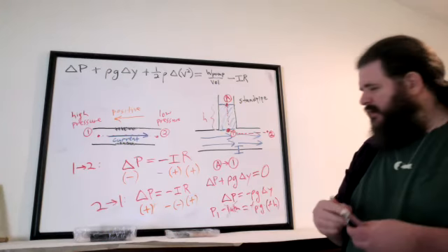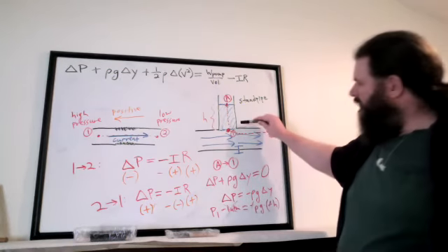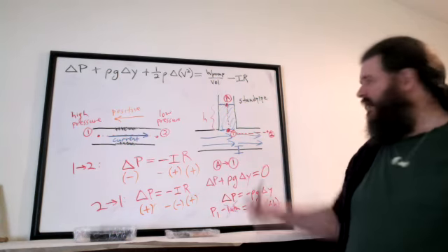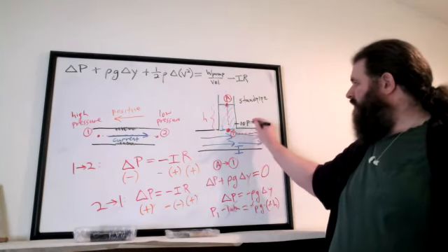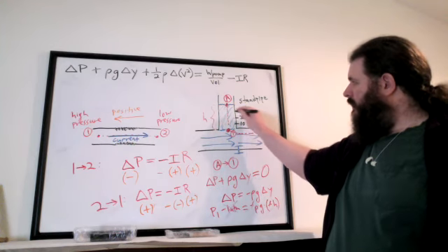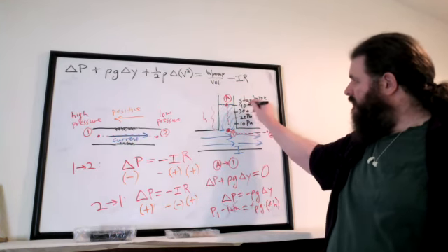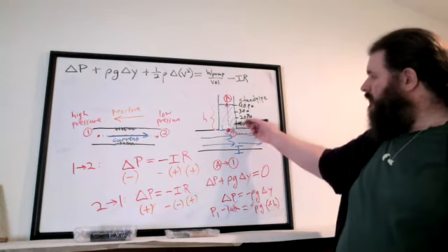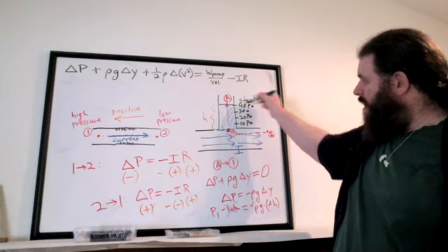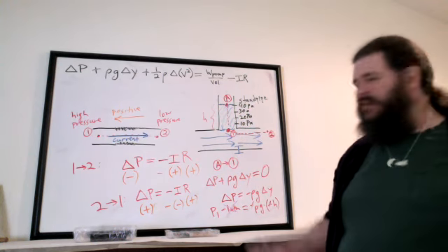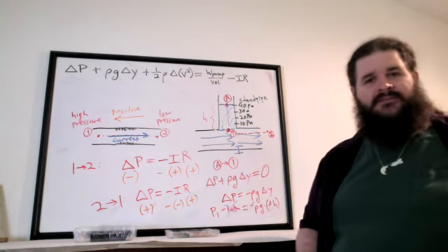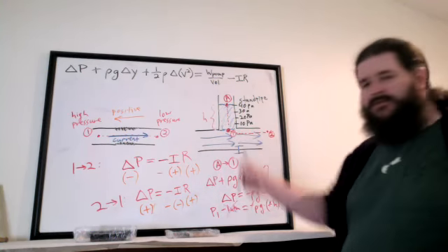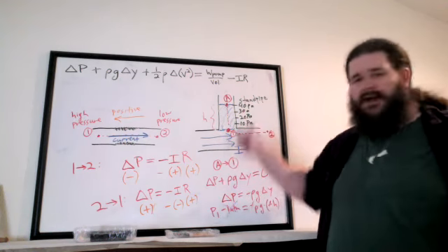In fact, usually you'll have markings on a standpipe like this. Instead of marking it in centimeters, you could mark it in pascals. You could mark this as 10 pascals, 20 pascals, 30 pascals, 40 pascals, and so on. If it's already been calibrated, you just look at how high the water rises and read off the number of pascals. That tells you the gauge pressure in the fluid at the bottom. So it's a very useful way of visually measuring the pressure inside some fluid system. Just look at how high the water rises in that standpipe.